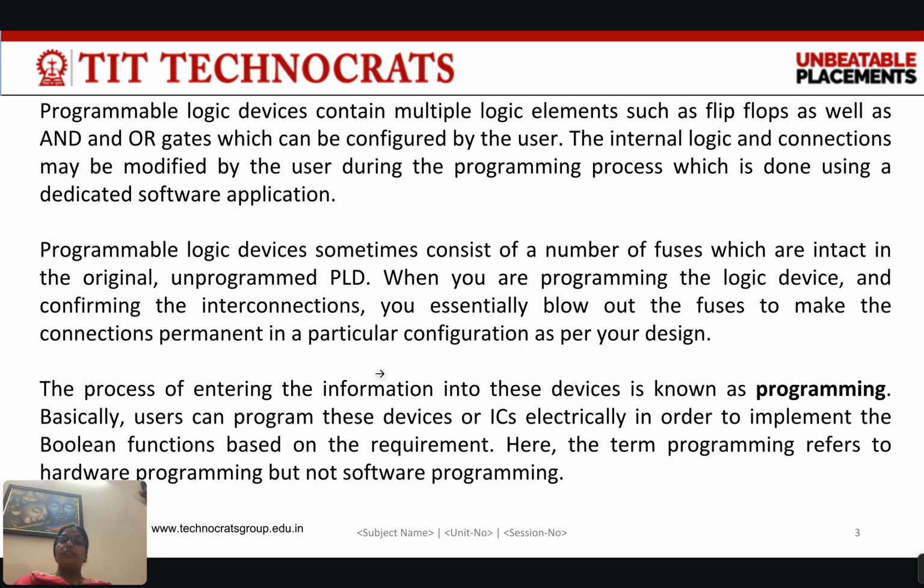Programmable logic devices contain multiple logic elements such as flip-flops as well as AND and OR gates, which can be reconfigured by the user. The internal logic and connections may be modified by the user during the programming process, which is done using a dedicated software application. Programmable logic devices sometimes consist of a number of fuses which are intact in the original unprogrammed PLD.